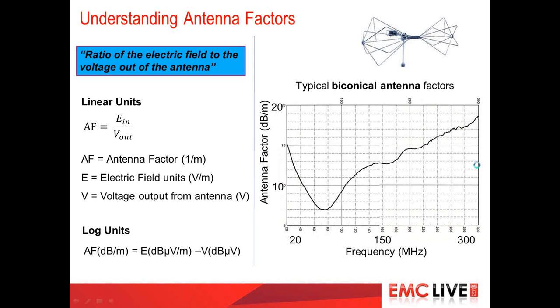We also have less expensive options, such as an OATS. OATS stands for Open Air Test Site. So these are going to be less expensive. They're outside, but the issue is that you need to have an environment that has low ambience. And that can be very hard to come by these days, considering a lot of people have cell phones, and really the spectrum is getting more and more crowded.